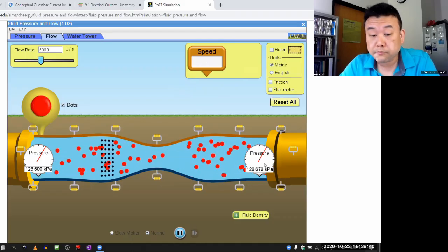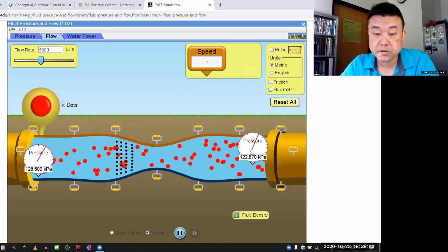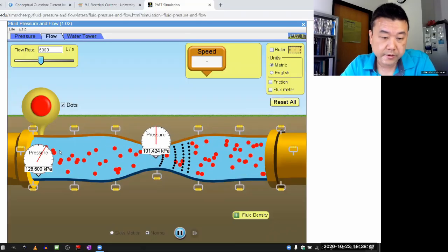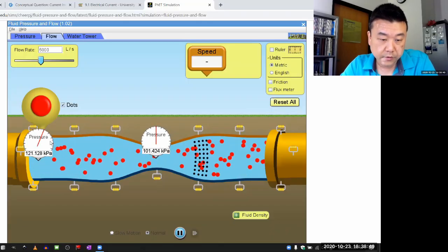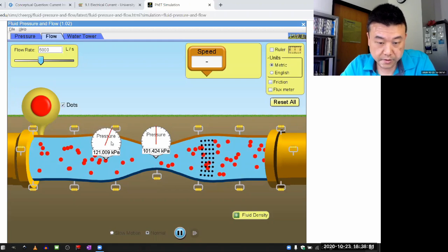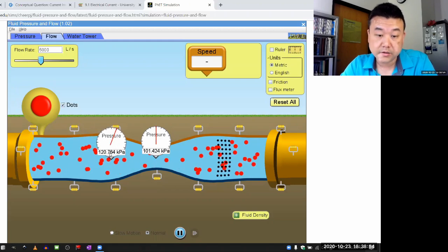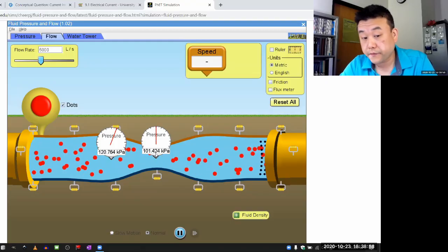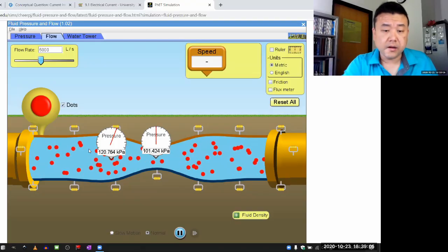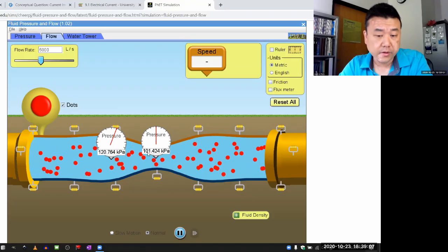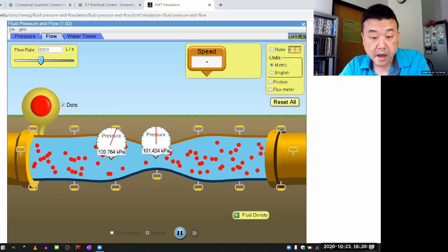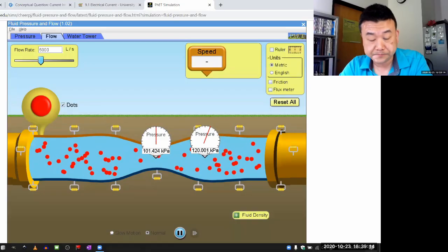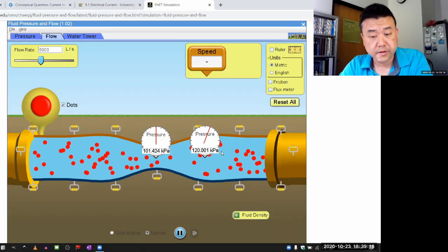And when you measure the pressure at different points, you see why. So this is entirely about fluids. So this fluid flowing from midpoint to here, there's a distinct pressure difference. So it's this pressure difference that pushes the water element through, so that it's faster here. And once it's through this portion, then the pressure difference is the other way, and that serves to slow them down.